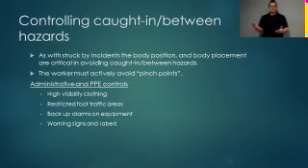So avoiding pinch points, a lot of times around crane swing radiuses or excavator radiuses, things of that nature. Oftentimes the controls are very similar to those that we see in struck-by incidents. High-vis clothing, but once again, it's mostly just body placement.